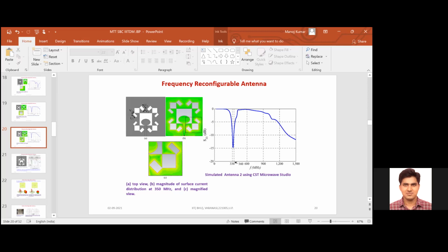Why are we changing the materials? Because suppose in the lower frequency you are working with RT Duroid or FR4 or something else like that. But in the higher frequency millimeter range, we cannot use the same material. RT Duroid, glass epoxy we cannot choose. FR4 you cannot choose.